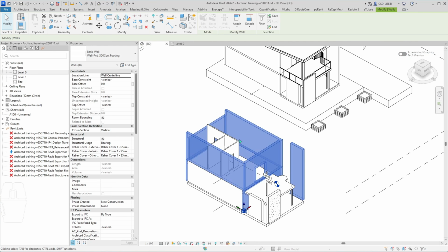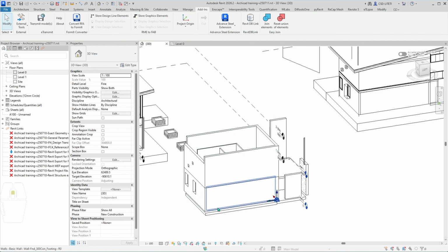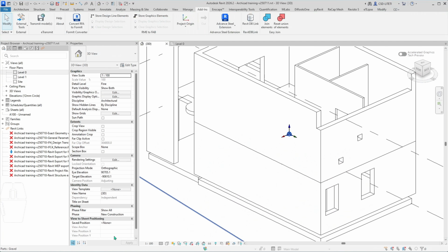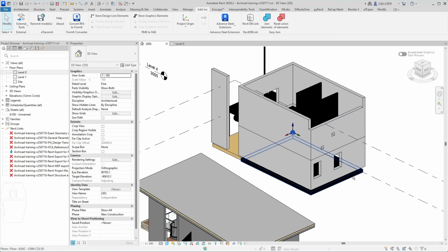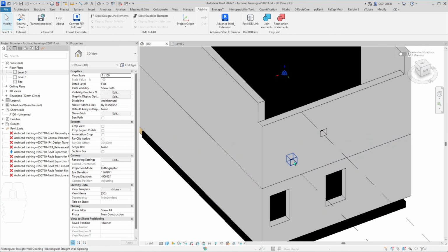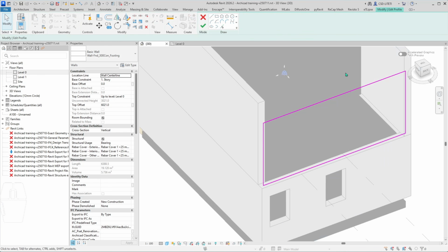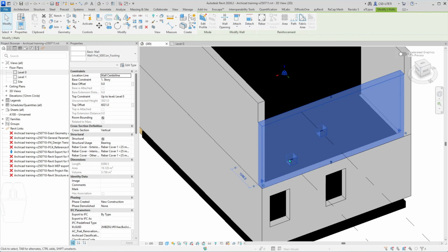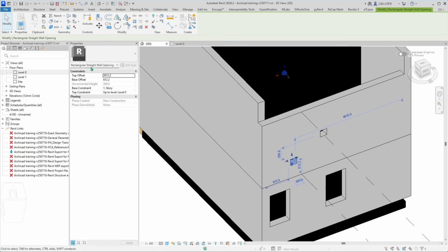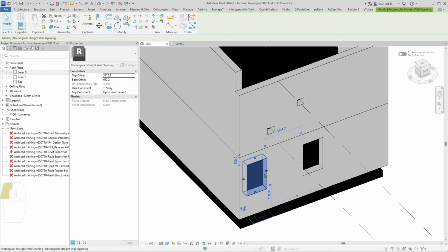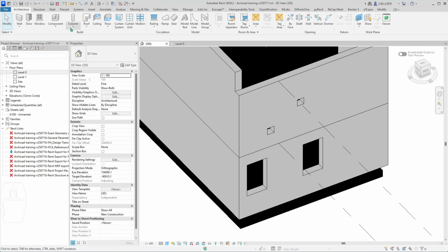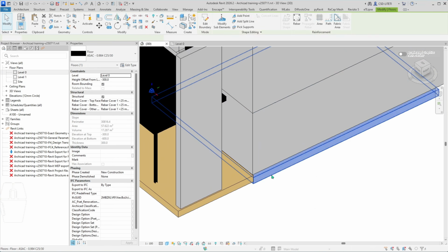And if I go to the 3D model, I see all my walls are changed, and they have a nice representation. Openings are clear. If I double click, I have a wall, and the openings are separate straight rectangular wall openings as usual from the architecture opening section. So these are openings created like that.